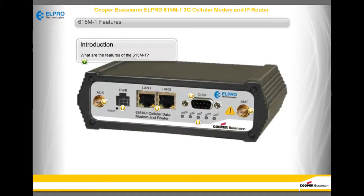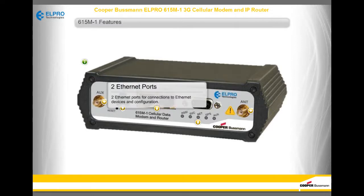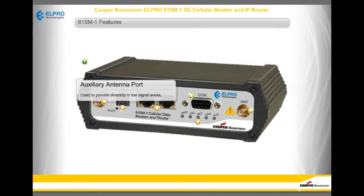What are the features of the 615M1? Click the glowing circles to learn more about each feature. Serial port. It provides connectivity for terminal devices, such as PLCs and remote I/O. 2 Ethernet ports. 2 Ethernet ports for connections to Ethernet devices and configuration.